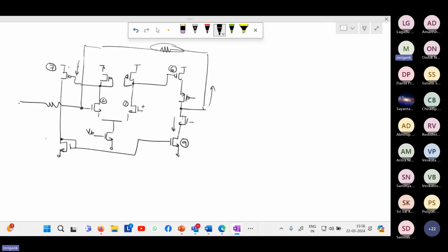It is a shunt connection. So whatever your voltage source is over here, I can convert this voltage source and this R into an equivalent Thevenin current source. Forget about this, and then I can consider the current input coming from here, and treat this as a current to voltage amplifier.